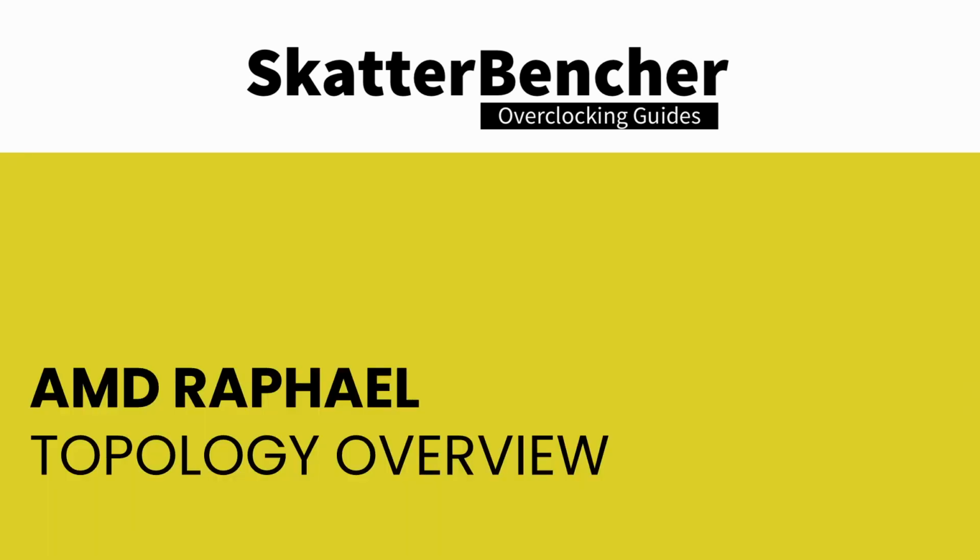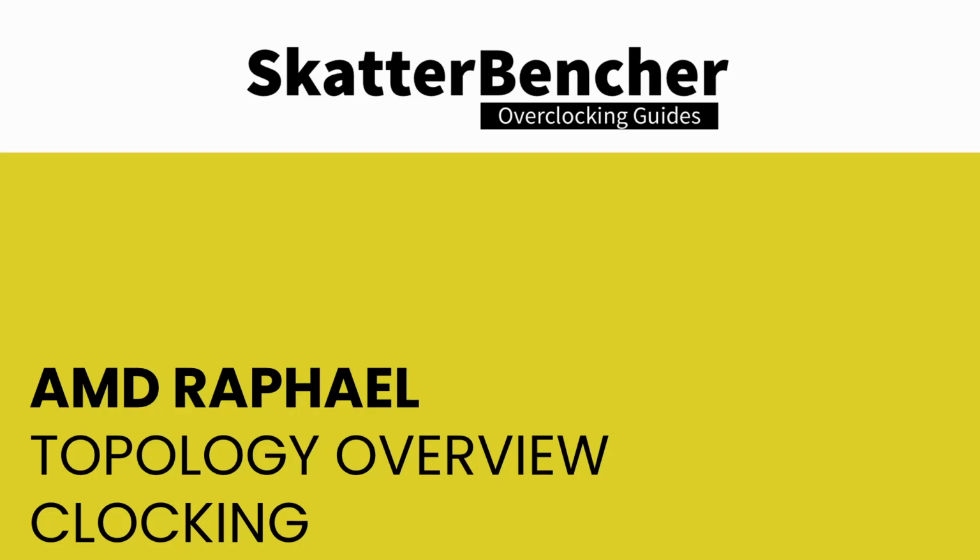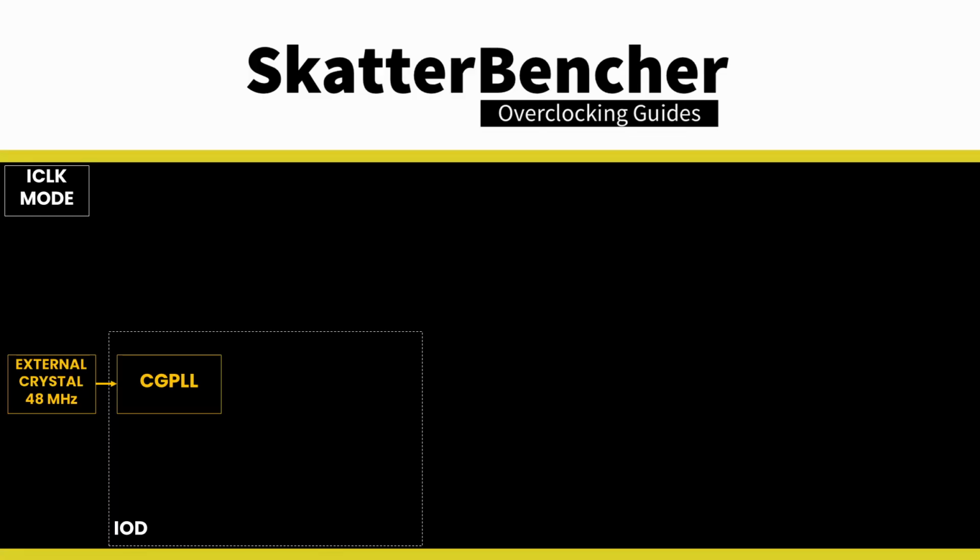Before we get to the overclocking, let's first have a look at the AMD Raphael platform voltage and clocking topology. The clocking of AMD Raphael CPUs is very similar to that of Zen 3 Vermeer desktop CPUs. The standard Raphael platform has a 48 MHz crystal input to the integrated CGPLL clock generator.